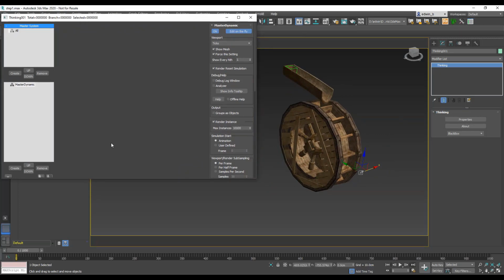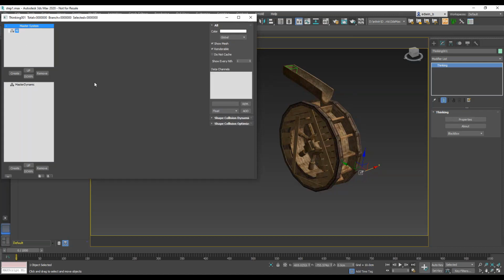So when I start with setting up visual effects in Thinking Particles, I usually create a base system or a basic setup that usually works for all visual effects. So the first thing is we need to decide on the particle groups. Particle groups are important, and they help us to control where and what particles are affected and how they are affected.